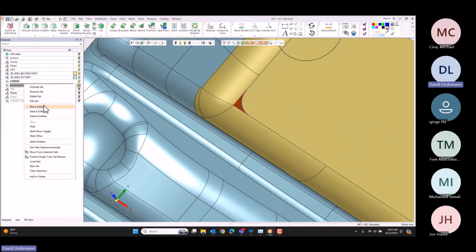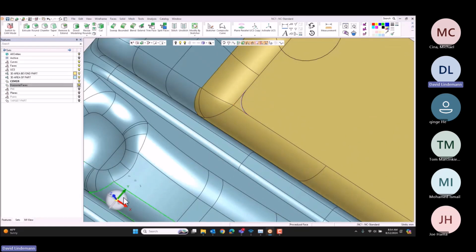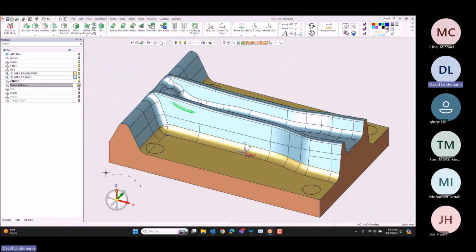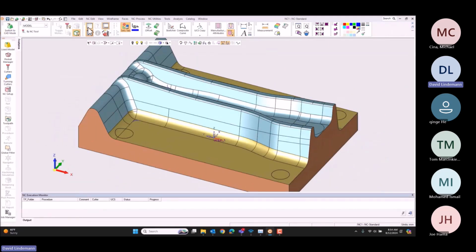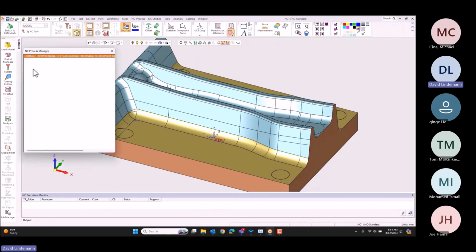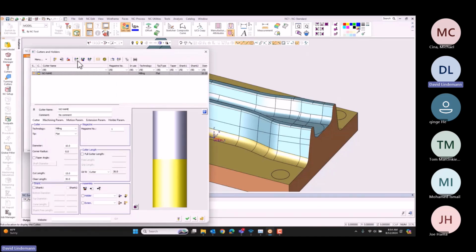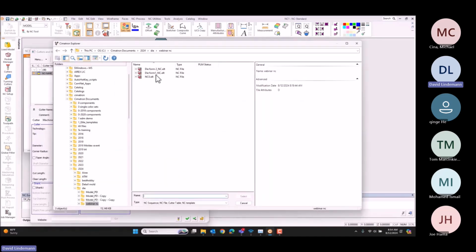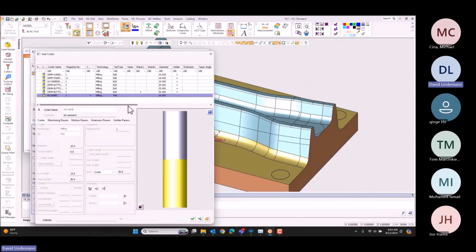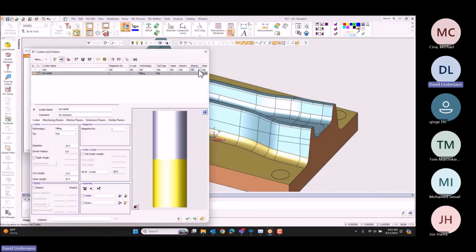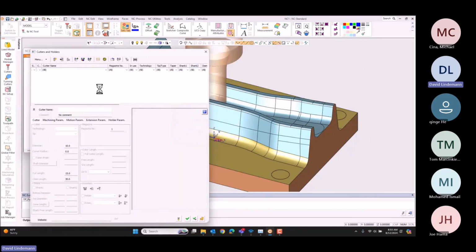And again, the idea is I want to capture that shape into the right little set I've got here. Set is like a layer or a level, if you're used to those words. And I can teach the system, I want you to cut this way with this set, cut another way with this set. All right, so now I'm loading my tool library. I can have several different libraries. All of them can be aware of the material that they're cutting. We can also manipulate these different libraries.